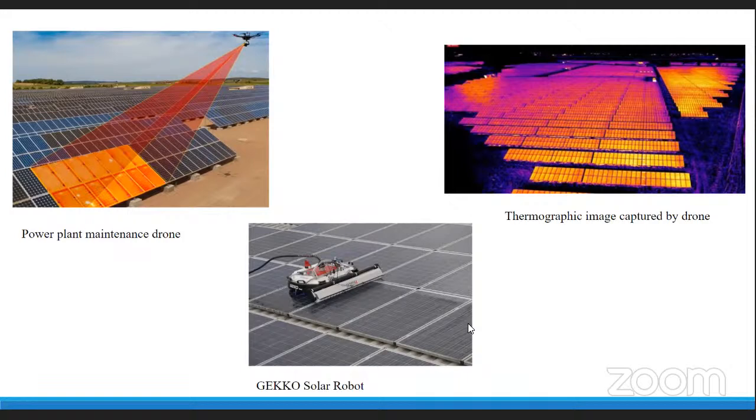or infrared thermography or electroluminescence offers a promising solution to this problem, where a UAV drone, as you can see in the image, will be flying above. It can get a bird's-eye view and see for any sub array, any table, how it's producing, and from it it can know whether there is anything that needs to be done, any string which is loose.